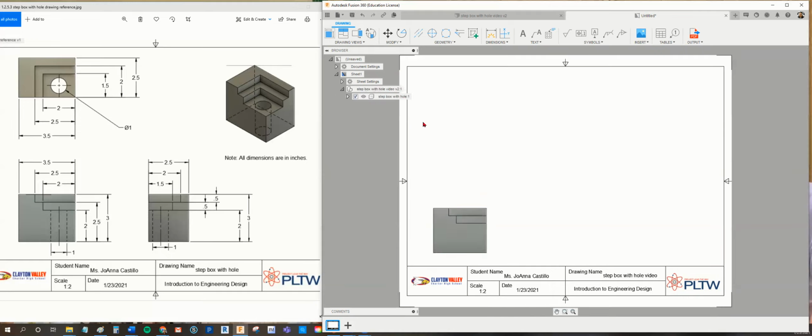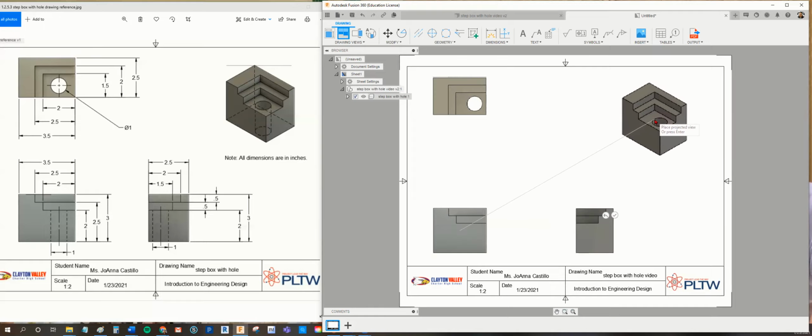All right. So now let's put the top view, the right view, and the 3D view. I'm going to go Drawing View, Projected View. You have to left click the parent view and then go up. I'm going to go far out a little bit so I have room for the dimensions. Then I'm going to go down and then right here, again making some room. Then I'm going to go this way here, and hit OK.